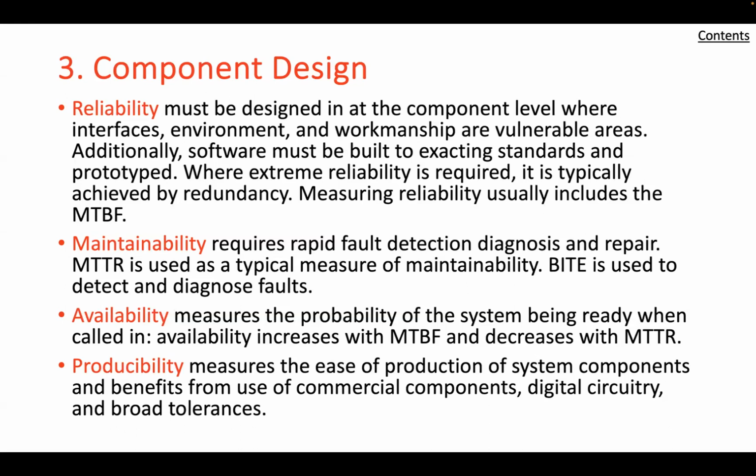Redundancy, increasing component redundancy, either with parallel operating components or through the use of switches that automatically transfer control and operations to backup components. Multiple functional paths, a technique to increase reliability without necessarily adding redundant components, involves including multiple functional paths within the system design. This is something known as channels of operation. There's also derating components. Derating refers to the technique of using a component under stress conditions considerably below the rated performance value to achieve a reliability margin in the design.